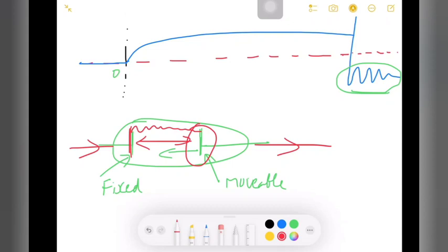That will give rise to a spark within this circuit breaker. You might have observed that the spark is seen whenever you open or close a switch. In a real-time system also, the arc will be present. To extinguish this arc, we make use of a medium. It could be SF6, or we can make use of nitrogen, or it could be your normal air, or some other gases.